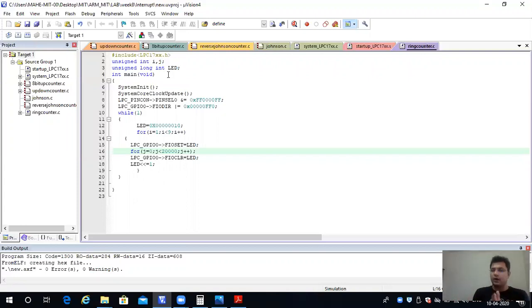Here the first function is the one we want to realize through configuration. So we will go inside the structure LPC pin configuration. This structure definition is there in lpc17xx.h.